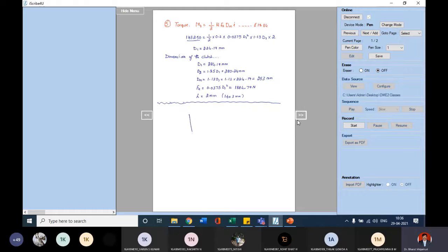Usually there will be a flywheel, which is basically made of steel, and there is a clutch plate. This is the only friction lining we have. The friction lining is only on one side, and on the flywheel you don't have any friction lining. In such cases I is equal to 1.